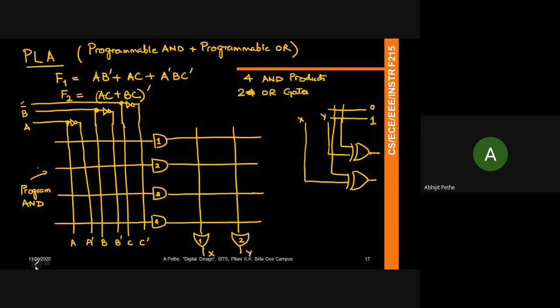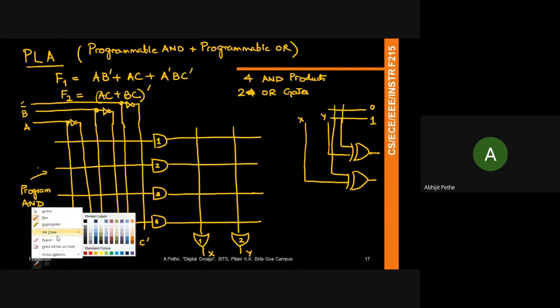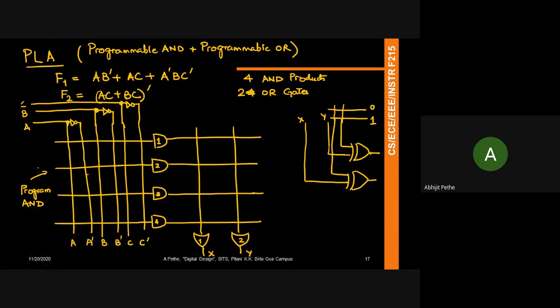So what I would do in this case is open up all other circuits and short only. In this case, for the first AND gate I will generate, I will say that this is shorted. I denote the short with an X, right? And I short B prime. B prime in this case is this line, right? All other inputs are open. So what this means is that the output I'm generating from the first AND gate is AB prime, right?